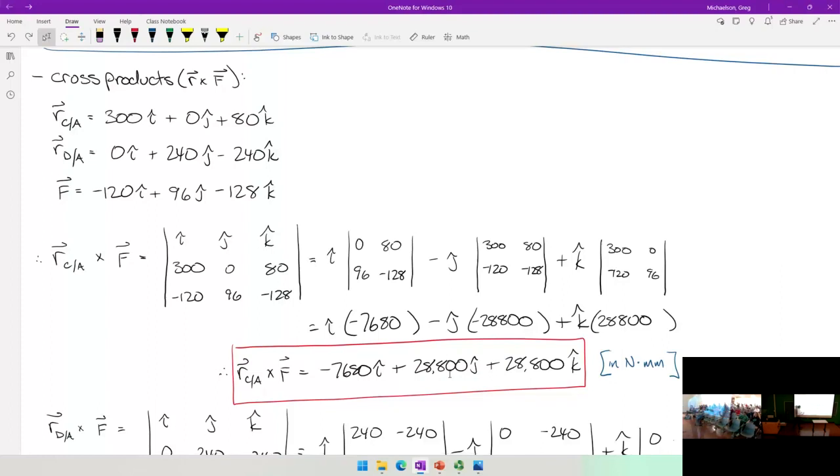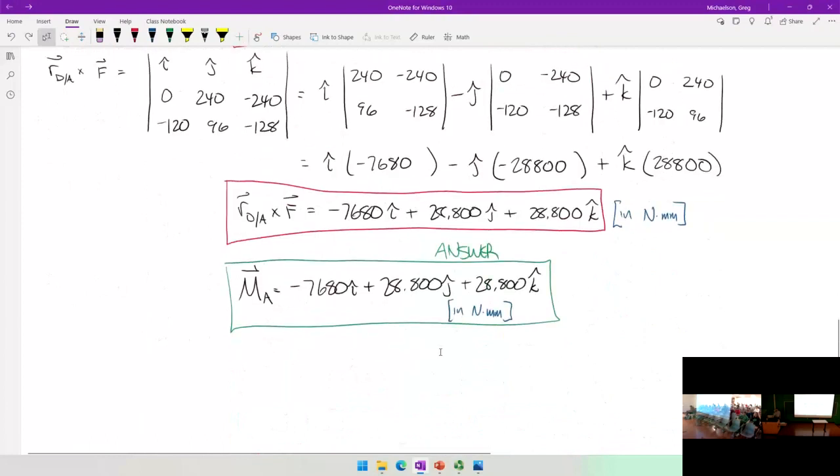So this is just a notation expressing how much this vector is wanting to translate the body in the X, Y, and Z direction. So where it says negative 120i, that means negative 120 newtons in the X direction. So imagine I have a coordinate system, X, Y, and Z, okay? And I have negative 120. That means I'm wanting to translate at a magnitude of 120 newtons in the negative direction of the x-axis. And this is how much I want to translate into y. This is how much I want to translate into z. Okay?